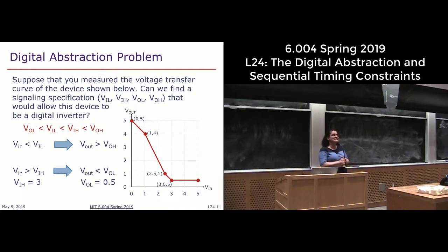It has to be exactly 0, right? But I need to have a little bit of room to play with. So setting my VOH to be 5 is too high for this device, right? So I need to set it to something lower, and I'm trying to figure out what that lower value might be. So just to keep things simple here, I'm going to try 4 next, okay?